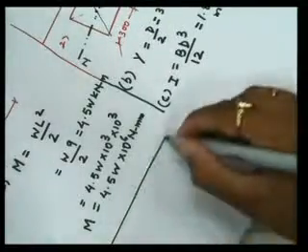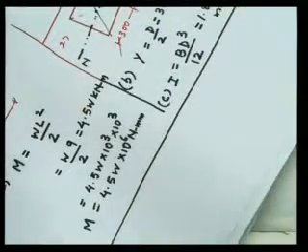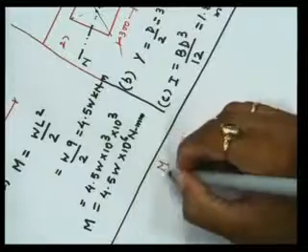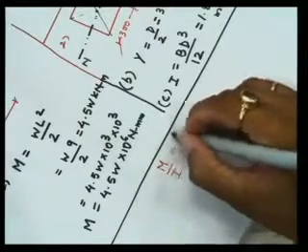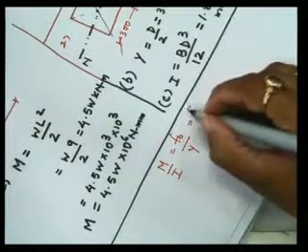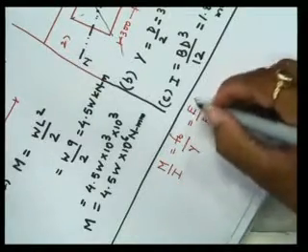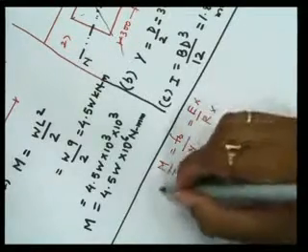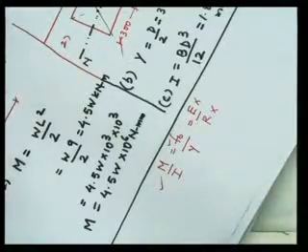Now what we are going to do? We are going to put it in our standard formula. What is our equation? How do we remember? M upon I, that is equal to FB upon Y, that is equal to E upon R. They have not given E, they have not given R, so we are going to use this both.